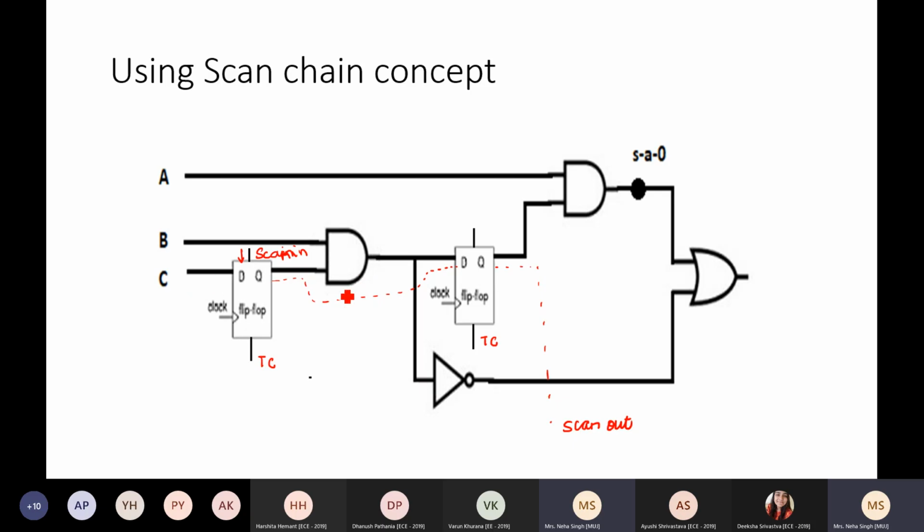So I need again only one test pattern, just like the previous case. The only thing was I reduced the number of pins. Though the flip flops are still there, I added only one pin at input and another at output. That was very easy to work with. At scan in, we have seen in the last class that the data is entered serially.